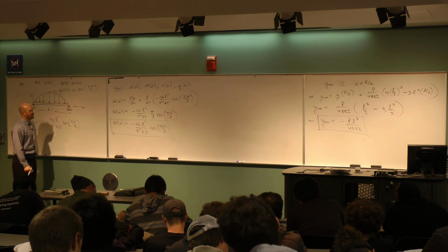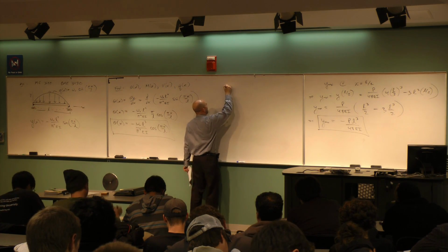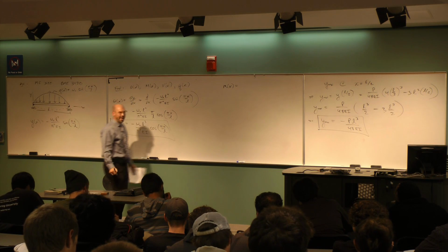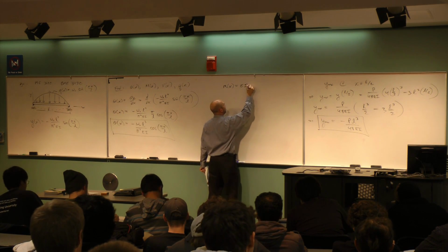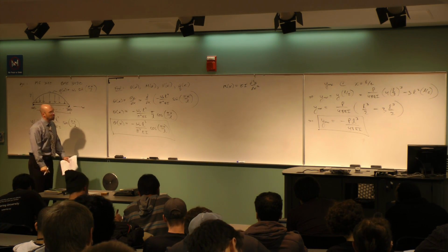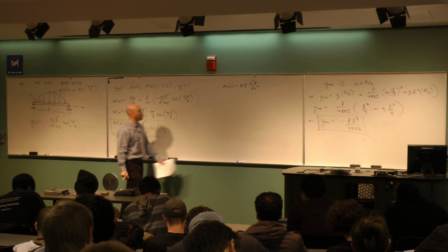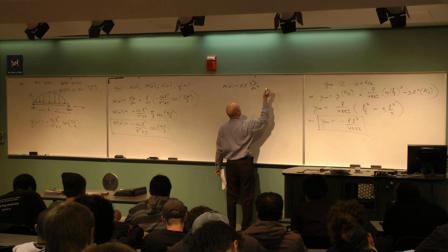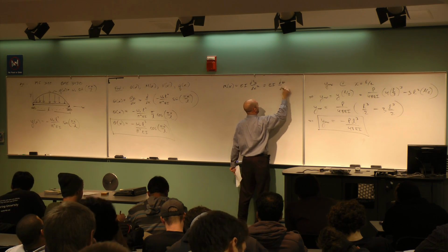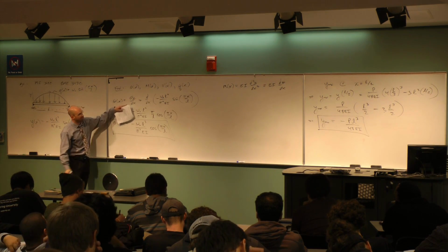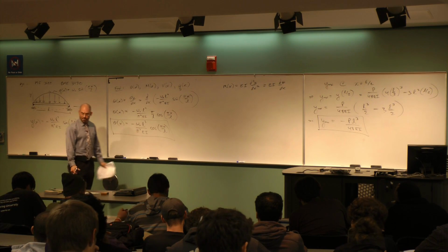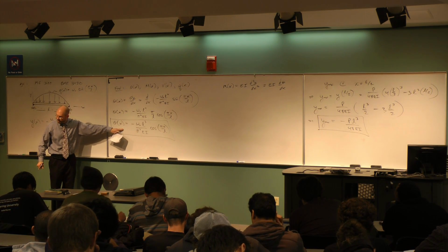All right, so how about the moment? Again, we wouldn't have you memorize this. If we asked you to do this on a test, we would remind you that M of x is EI times the second derivative of y with respect to x. That is called the moment-curvature relationship. The second derivative is curvature, essentially, if the angles are small. So this is the same as EI times the derivative of theta, because theta is the first derivative, so the derivative of theta would give me the second derivative. So the point is, I just keep going: take this guy, multiply by EI, and take the derivative.